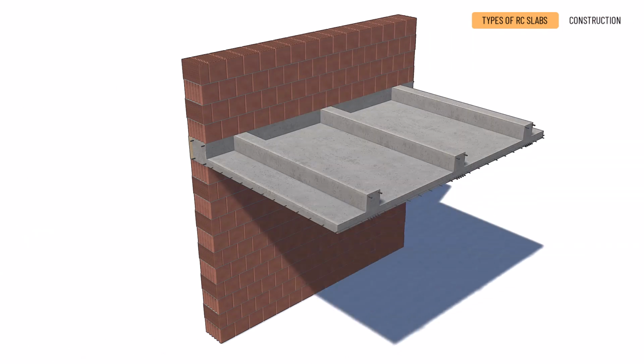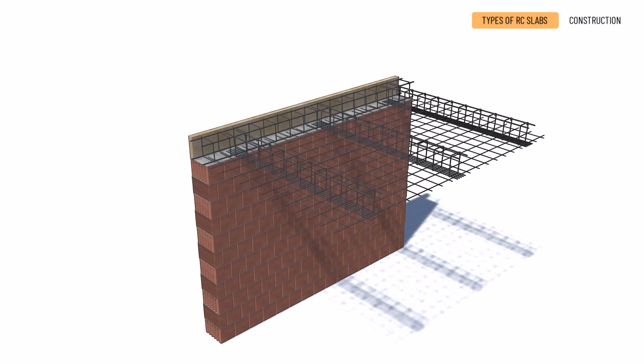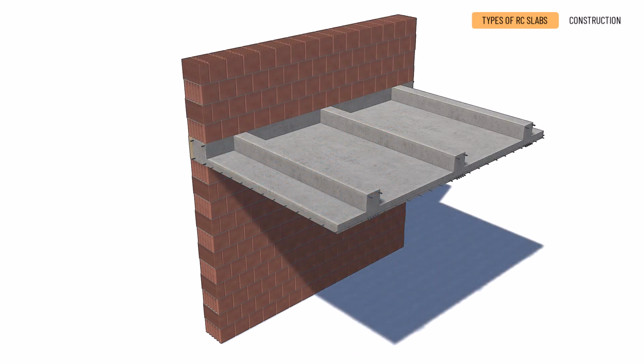Upstand reinforced concrete slabs. For an upstand slab, the ribs are positioned on top of the slab. The load-bearing capacity of such a slab is significantly lower than that of the downstand version. Formwork is not easy to build. Although the space between the ribs can be filled with larger mechanical ducting, a false floor must be installed or the voids filled to create the floor level.